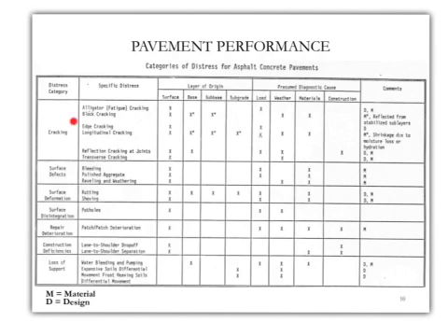When it comes to block cracking, it's a combination of weather as well as a materials problem. And let's talk about surface disintegration, potholes. Again, if you go all the way to here, the major reason is loading as well as weather. The very first thing is definitely loading, because we have repetitive loading on a certain point that is kind of weak. So this is the way it's going to initiate. And then the weather, what I mean by weather here can be temperature or water. In this case, for potholes, it's mainly water.